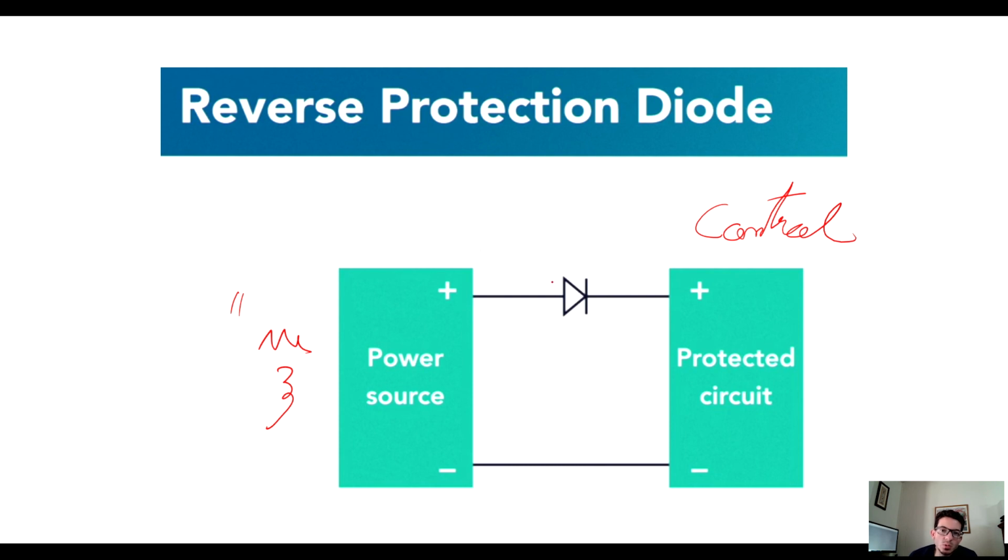So in this particular case, you would use a diode. When the current is flowing normally, then you have the values of current and voltage that you want. Remember, to let this current happen, you have to provide a voltage that is greater than your forward bias voltage, which is 0.7 volts. So you need more than that. And for instance, if this is supposed to be operating at 3.3 volts DC,